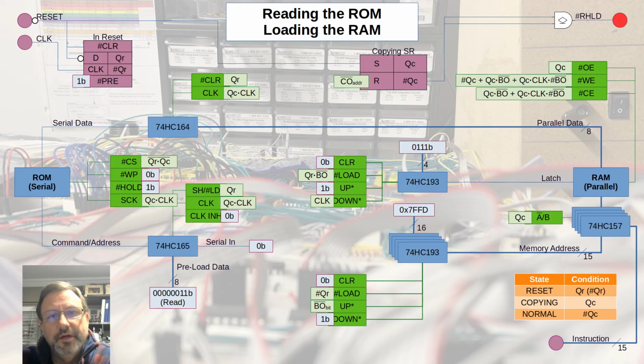Also, the emulator is almost guaranteed to work or not work. There's one way to hedge my bet there. The way the emulator is architected, there are no timing issues. Ultimately, things happen sequentially, and there's nothing that takes into account the fact that there may be some delay in one circuit or one IC that is longer or shorter than the delay in another IC. And so I may have success in the emulator that I won't see in hardware.